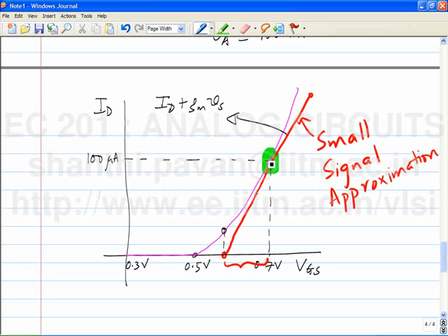However, even though the transistor is not truly cut off, the transconductance is reduced quite dramatically, which means that the incremental gain, though not 0, would have reduced a lot from the value we calculated for small signals about our operating point.